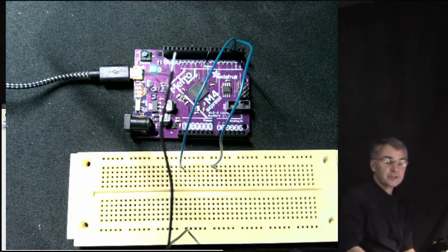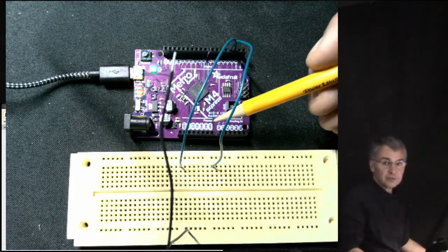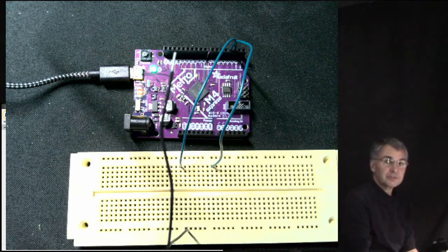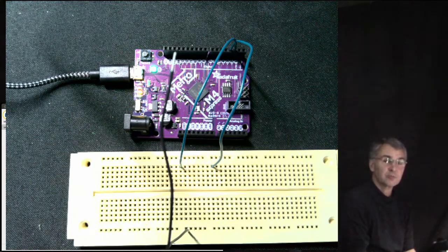Ground is the reference point on our circuit that we refer to as 0 volts. So really only voltage differences matter rather than absolute voltages. So you can measure voltages with respect to some reference point on a circuit. And conventionally in electronics we call that reference point ground. We say ground is at 0 volts, and then we measure other voltages with respect to that ground point. Because you know from your study of electricity that voltage is always measured between 2 points on a circuit. So when we speak informally, when we're doing electronics, we say the voltage at a point. That means the voltage between that point and ground. So there's always some reference point called ground, which is one of the 2 points between which we measure voltages.